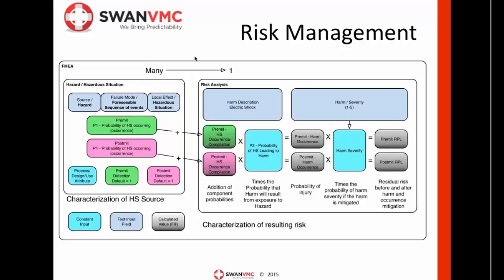Well, you can imagine that there's lots of different ways to energize a case in a design. So you might have 3 or 4 of these different hazardous situations defined. And, as another example, maybe you pour water on the case, and that creates a short and energizes the case. So in one way or another, we end up with these different situations that could lead to a case being energized. Well, the P1 factor is the probability of that hazardous situation actually occurring.